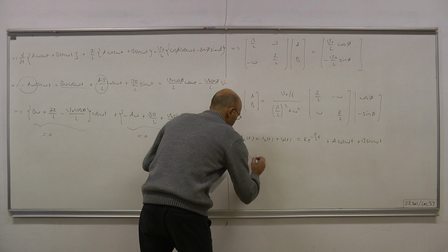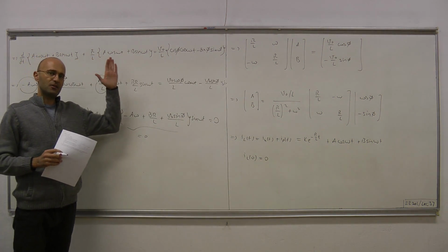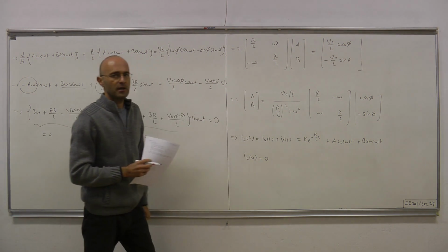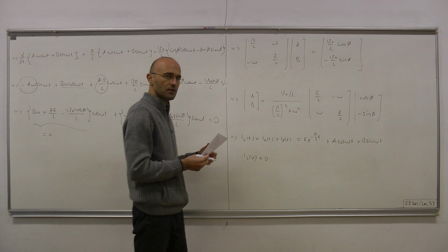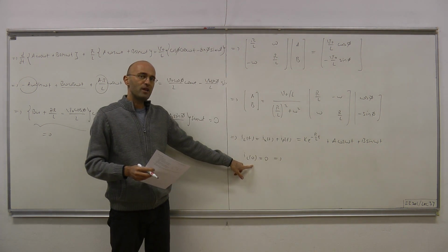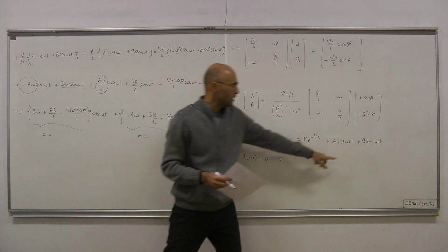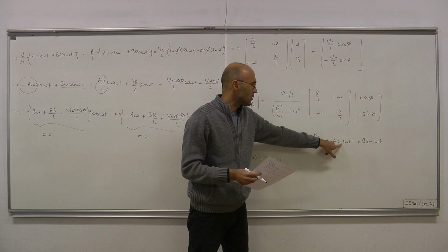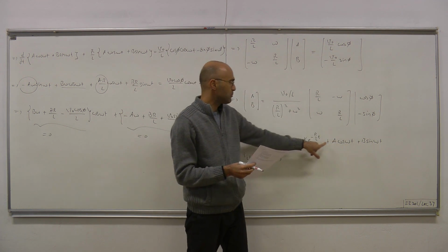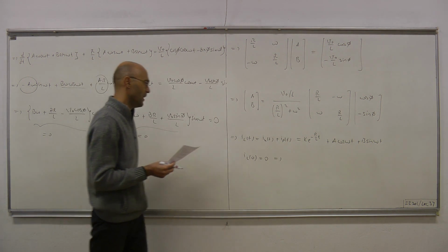To determine k, we use the initial condition constraint. Due to the fact that the switch was open, I_L(0) equals 0. So the initial inductor current is 0. That constraint has to be applied to the overall solution I_L(t). Plugging in t equals 0, sine goes away and cosine is 1, and this exponential is also 1. So what we have is k plus a equals 0.